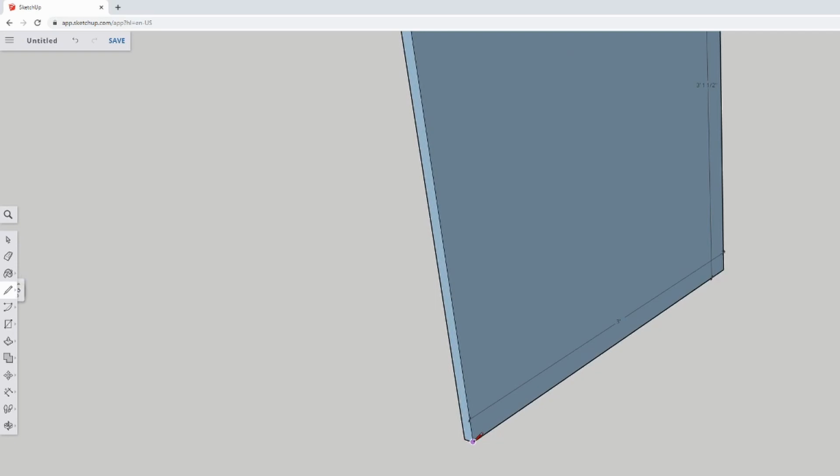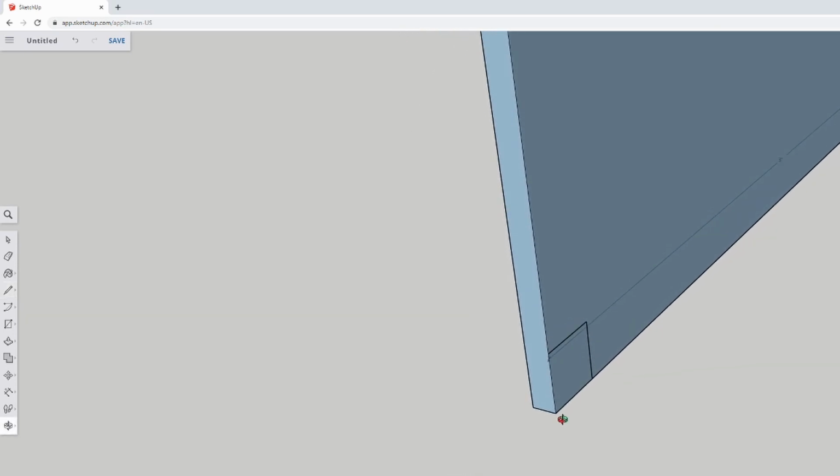So I'll come down here to the bottom corner and create a cutout that is 2 inches by 2 inches. If I go from here and come out exactly 2 inches, and I can see that because I can see the length down in the bottom corner, I can create a point. And now I have this reference endpoint. I can go up 2 inches here, and then create a point back. Now this creates a little square.